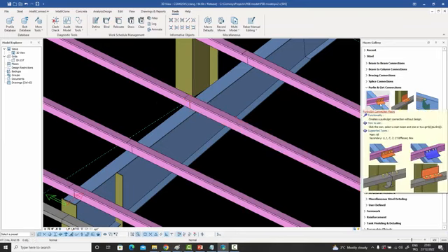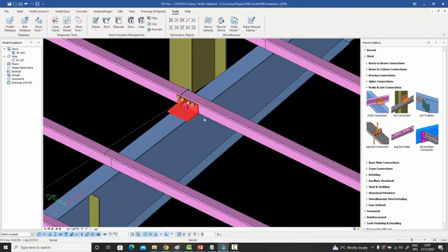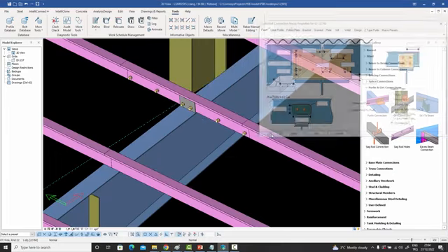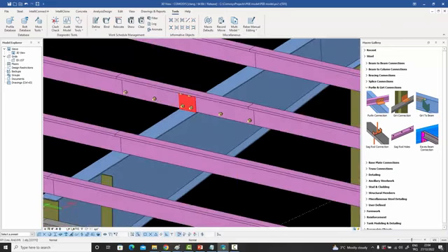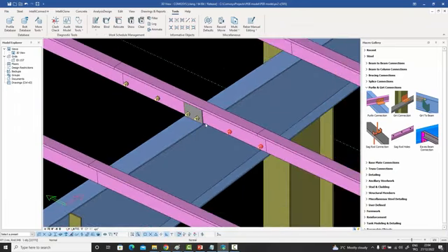Now, very simply, what we can do is we can use the normal purlin connection, select the main beam, select the Z profiles, and we get our standard angle connection, or whatever the default is. But if we go inside the macro now, we have this option of the overlapped Z. And if we select that, immediately an overlapped Z connection is created. And what that means is that this purlin is extended to the other side, the other one is extended into the first one, and we have a plate connecting the two with 4 bolts. But then there are other bolts as well, which are just connecting the two purlins to each other at these points, according to the need.